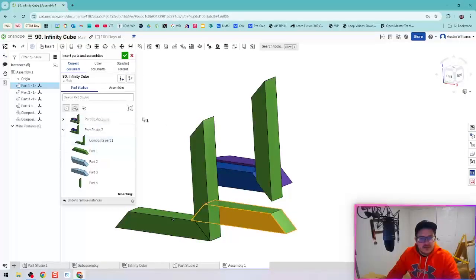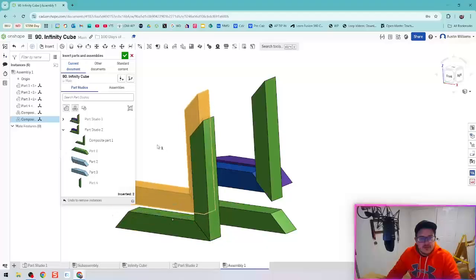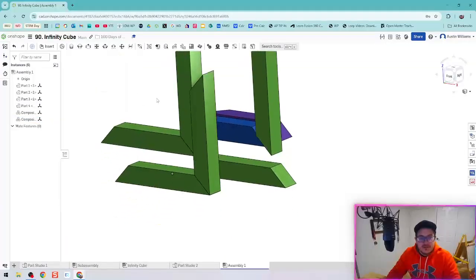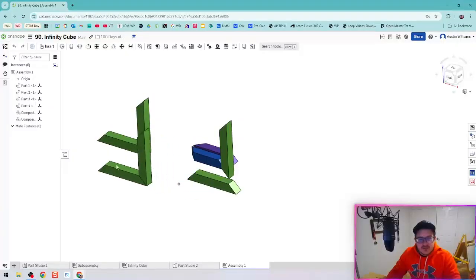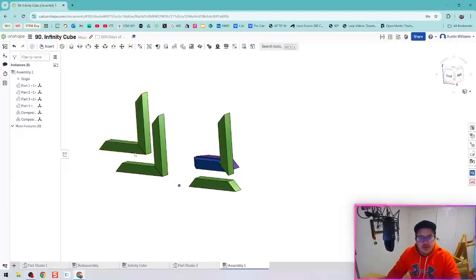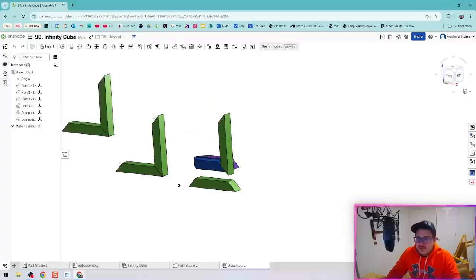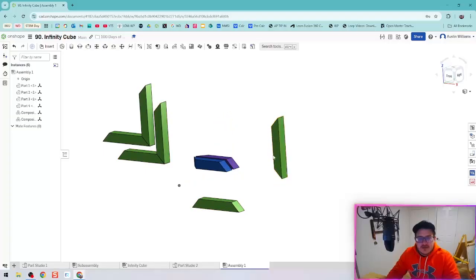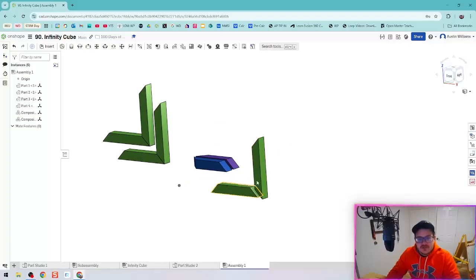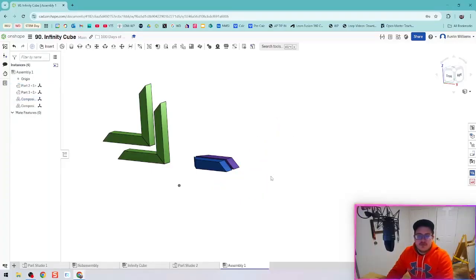So this is a good time, let's pull in that composite part twice, to talk about when's a good time to use a composite part versus when's a good time to use individual parts. Since I made a composite part of my corner bracket, notice they're already moving together. I don't actually need to do a mate here. But since I pulled in all the parts individually originally, these 2 parts can move independently of each other. So I actually don't want these pieces. I'm going to click on once and delete them and say, bye-bye, adios. And then we're ready to start cooking.